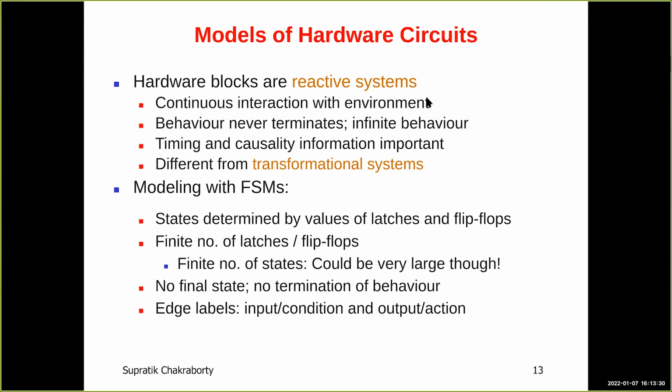So what we will do is we will treat hardware blocks as reactive systems. We've already talked about reactive systems yesterday. So there's a continuous interaction with the environment, and these are different from transformational systems or functional systems, which just given an input generates an output and stops. So we will model these using finite state machines, and the states here are determined by values of latches and flip-flops. Of course, any hardware will have a finite number of latches and flip-flops. So the state space is finite, but it can be very, very large, right?